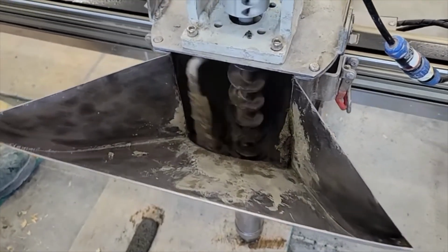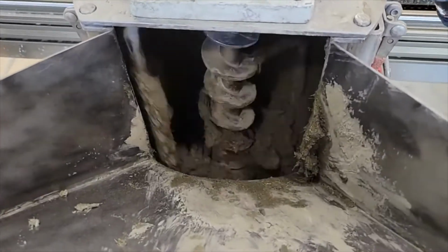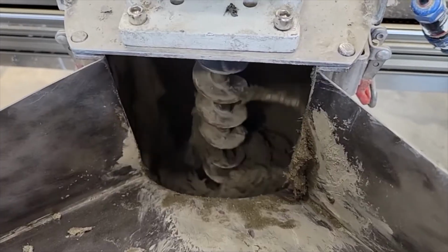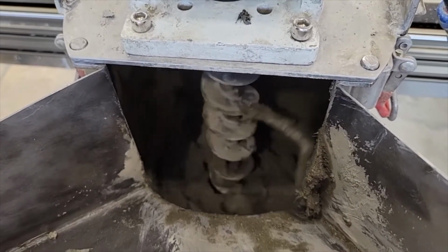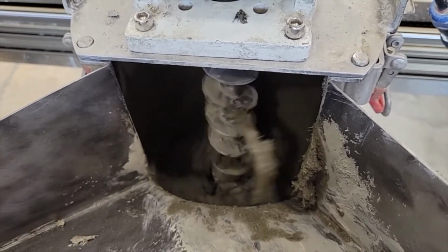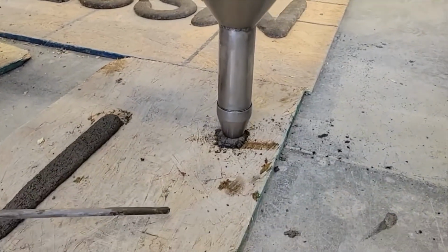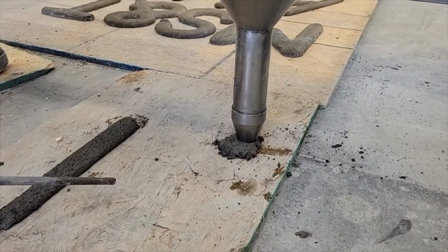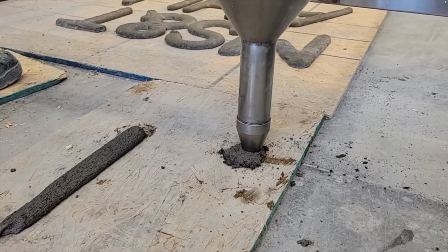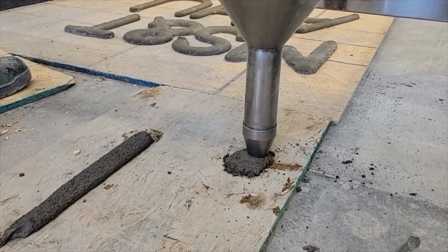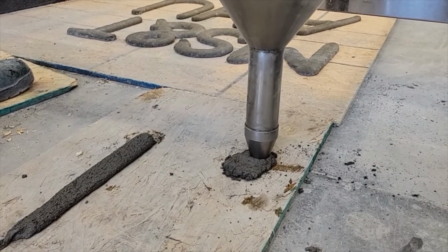Aggregate or fiber blockage is a common issue if mixture proportion is not well designed. The experiment shown here is a fiber-reinforced concrete mixture in which fiber clumping occurred and blocked the nozzle. In this case, it doesn't matter how much force we apply to this mixture, it is not coming out of the nozzle. In case of blockage, increasing the load capacity is not helpful.